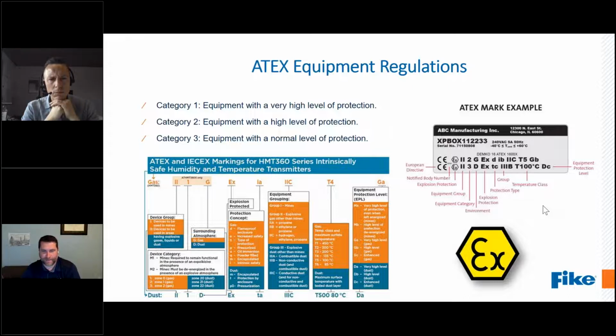Everything has to have that in a rated location, and there should be documentation that goes along with it. That could be certifications, there could be calibration documents. You need to maintain all of that in your EPD, and it's on file for anything in those hazardous locations.